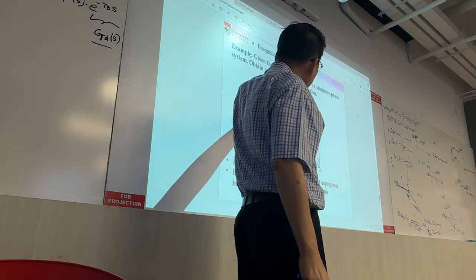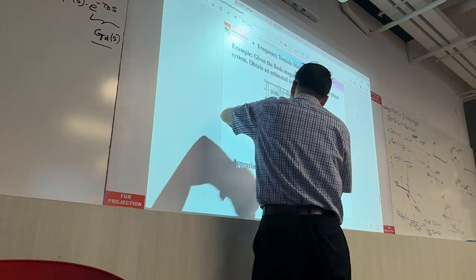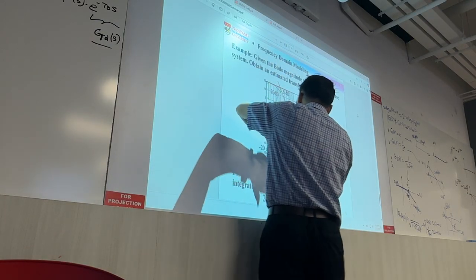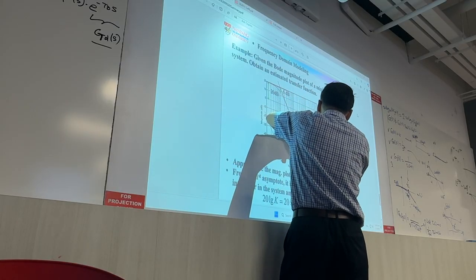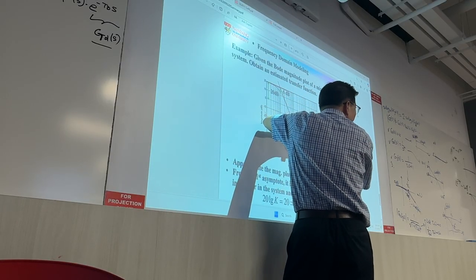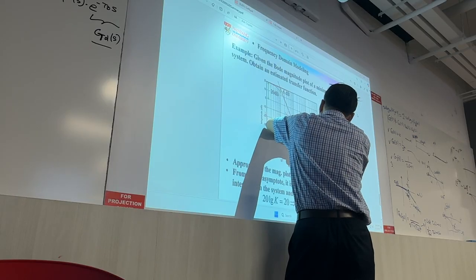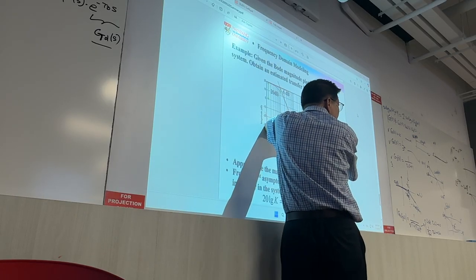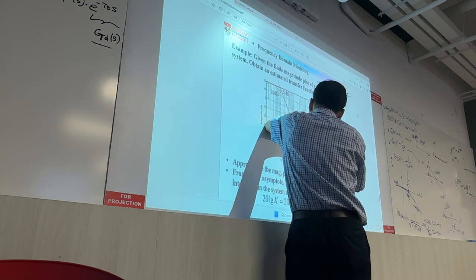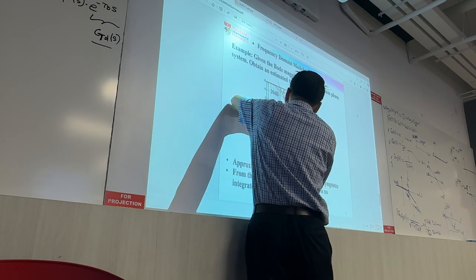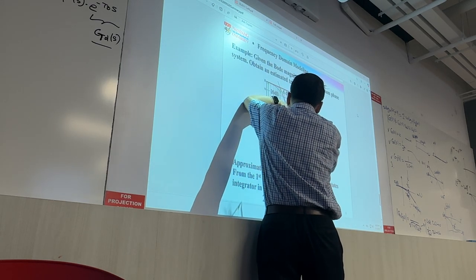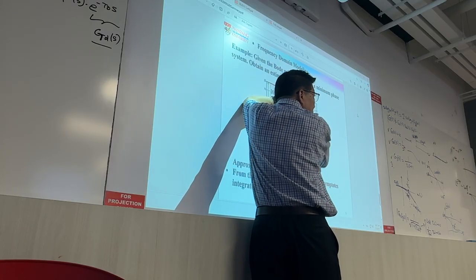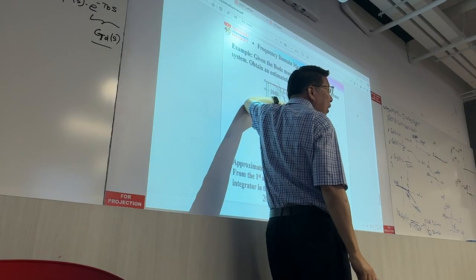All right? So we try to use this to fit, you move it parallel to fit into this. If we are able to fit the minus 20 dB per decade, that means this is due to a first order system. If we use a minus 40 and shift, and we can fit in a minus 40 dB per decade, that means that this is a second order system.